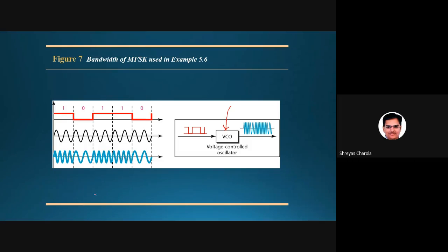Digital signals have only two voltages. For logic 1 it is 5 volts, and for logic 0 it is 0 volts. Based upon that voltage, it controls the oscillation. Here you require more oscillation, here you require less. That means we need to control our oscillation based on the input voltage. That's why we use a VCO where the input signal is a digital signal.